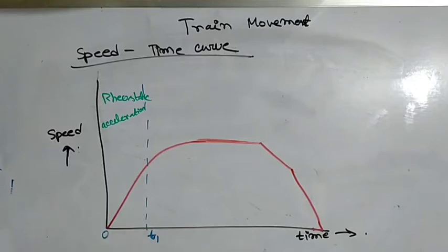Now tractive effort is defined as the force in newtons exerted by the driving wheel on the rail to produce the movement, and the sum of tractive efforts exerted by all the driving wheels of a locomotive is called gross tractive effort, which is proportional to the combined torque exerted by the motor. Motor current during the notching up period fluctuates between certain maximum and minimum limits, and therefore the torque developed by the motor and the tractive effort also fluctuate.